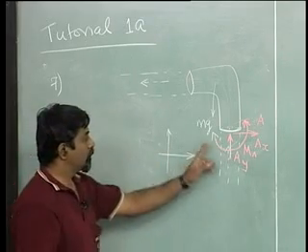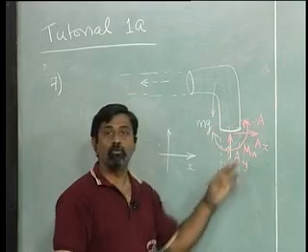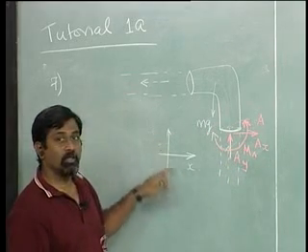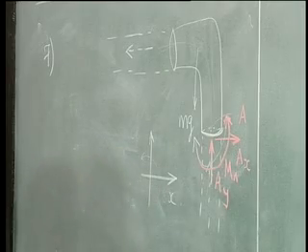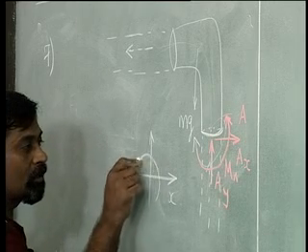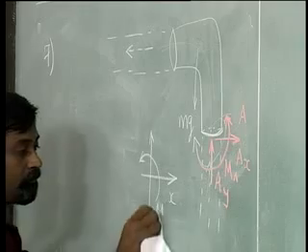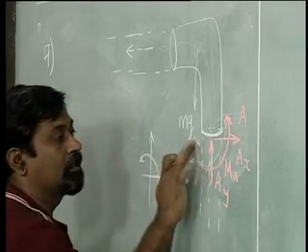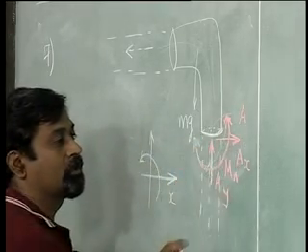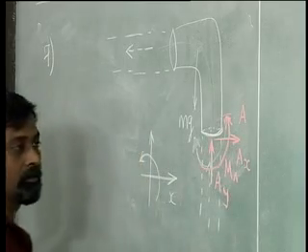Okay. So, in this particular case, whichever is an unknown force, I will use the directions which are positive. Okay. And as you can see, anti-clockwise direction here can be taken as positive for moment. Okay. That is the reason why we have used MA in this direction.